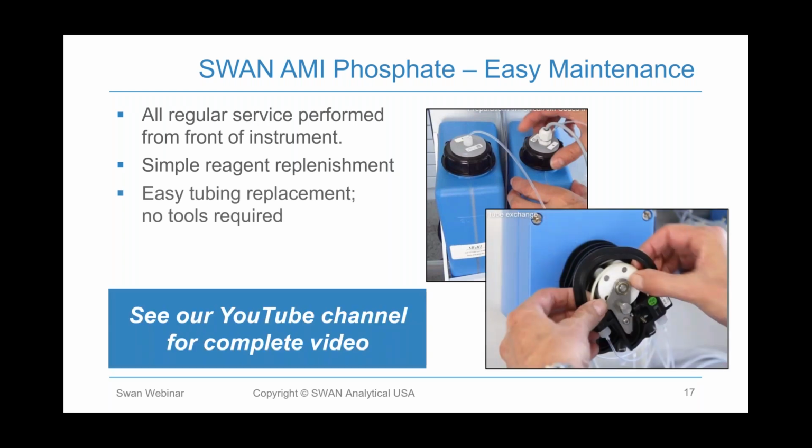So you can see this is a picture of us taking these preloaded, what we call paraclips, off of the front of the analyzer. And you can see, if you can see my cursor here, these 2 little ferrules here at the bottom, you unscrew these 2, you pull the old paraclip off, you unscrew these 2 ferrules to the new tube or the new paraclip and replace it back on. It takes about 5 minutes to do. That's done twice a year, and that is the only scheduled preventative maintenance part that needs to be replaced.